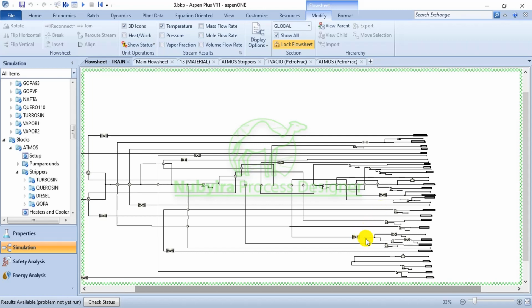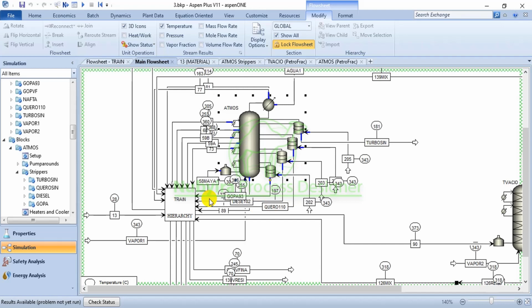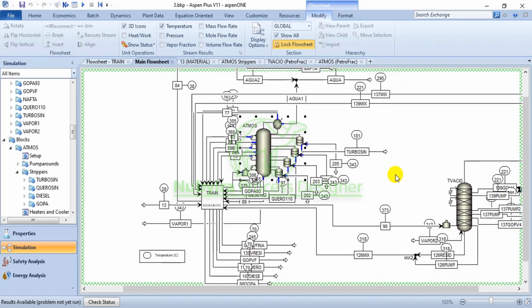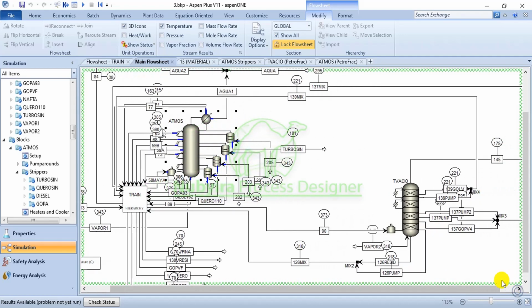because we must cool down the product as we are drawing it out of the atmospheric and the vacuum distillation column. For example, this is the aviation fuel drawn out of the atmospheric distillation column, and this is the stripper for it. Then we have the kerosene. It is cooled down in the heat exchanger train, and the diesel and the atmospheric gas oil, while for the vacuum column too, this is done for both the pump around stream and the product stream.